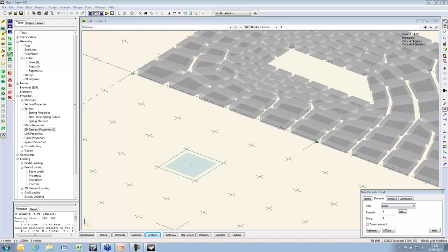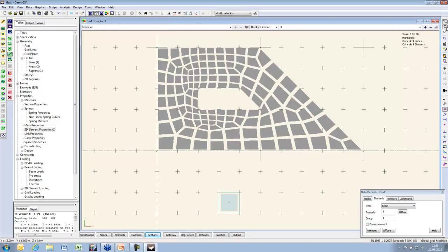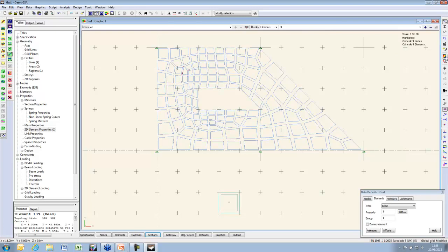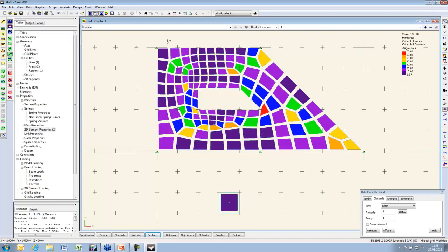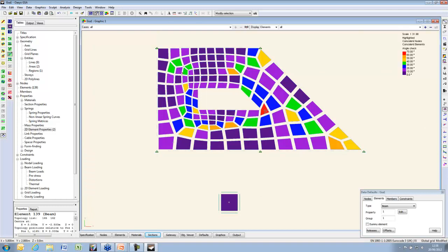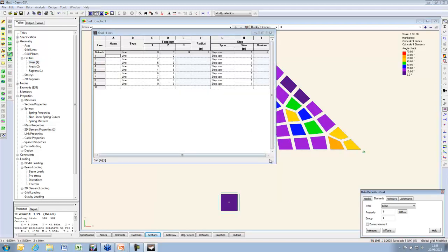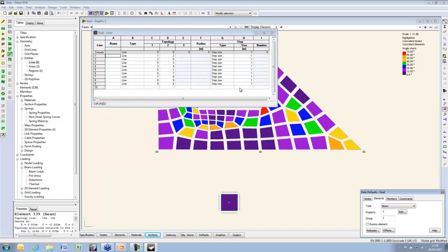Okay, let's take this one here. In fact, I think there are some elements in here which are getting a touch unrefined. Let me contour them by their angles. And you can see there's this chap down here, which is beginning to look a bit coarse. Now, there are a number of ways that you can adjust this. One of them is to adjust, if possible, the step size in the adjacent lines. Sometimes you're going from a large to a small area. Changing that can help.